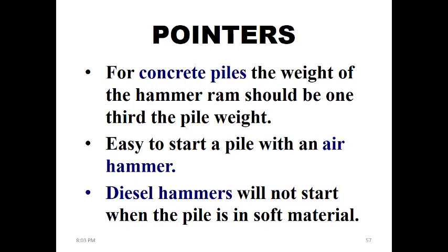If we do not have compression, then the ignition wouldn't happen and it wouldn't be easy to drive a pile with these diesel hammers. That's why I mentioned that for certain situations you will need to start the process with one type of hammer and then continue with another. So there are different factors to consider for using different hammers for that same pile.